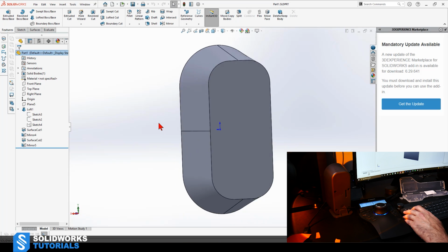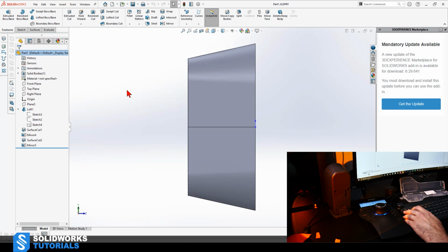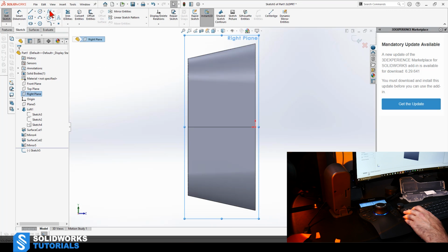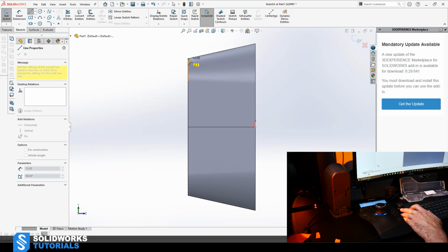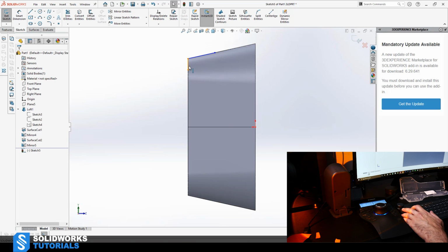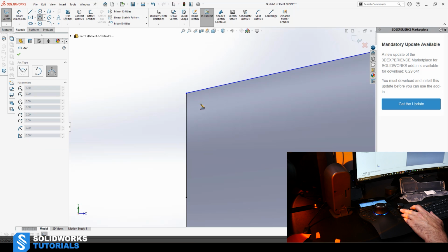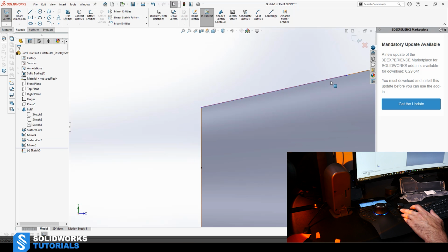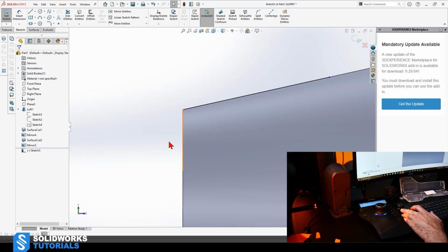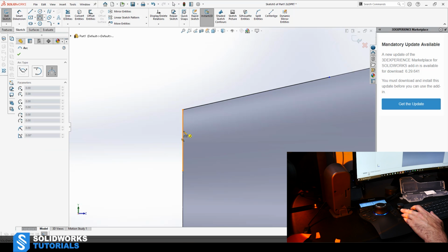I'm gonna pick the right plane, activate the sketch. I'm gonna draw one sketch from here to here, one from here to here, and I'm gonna use 3-point arc. Yes, this is the best way. Let's quickly fix this line because it's just for reference, no use for them. And I just wanted to have this angle here, and I don't need to measure it again because it's already existing here. I'm just gonna build upon it and get the radius I want, and then go back and use fillet, and then use that fillet.